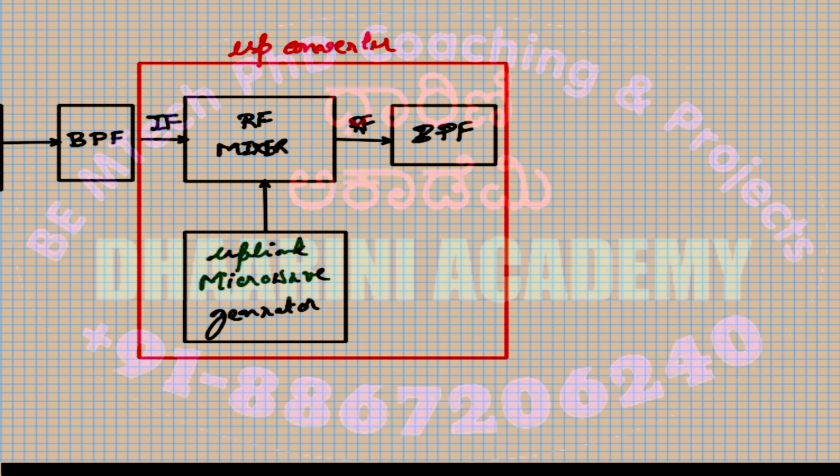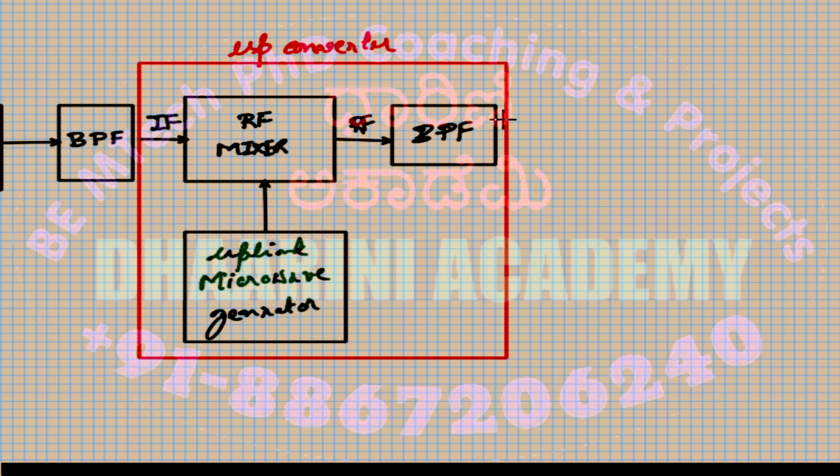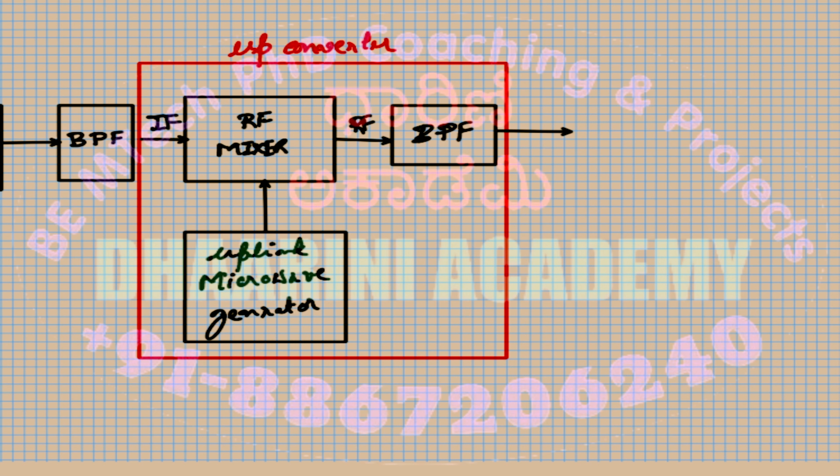From the up converter, the output of this band pass is then connected to a very high power amplifier, just to give the required power. Its properties are not changed because the message has been converted into high frequency, only the power is required.